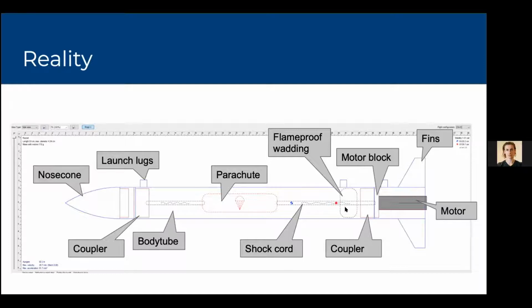You have to consider a very important lesson that I learned the hard way, a motor block. Basically, you have to stop the motor from getting pushed up inside your rocket. Seems obvious, but definitely something you have to pay attention to in your design, and also making sure that it's strong enough to withstand the forces that your motor is going to be exerting, both during flight and when the ejection charge fires, which is a small explosion of black powder.